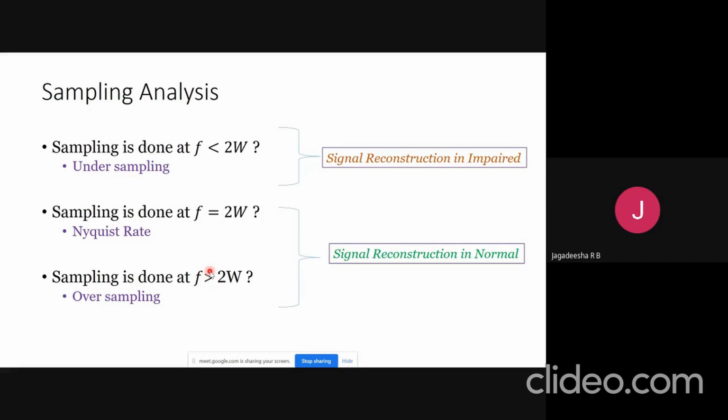But if you collect just one sample in a sine wave, either from the positive half or negative half, then you cannot represent it as a sine wave, right? So that's the issue with undersampling. This is a simple intuition to think about the Nyquist sampling rate. They said this should be 2 times or more than 2 times. Of course, a formal proof you can find in the literature.